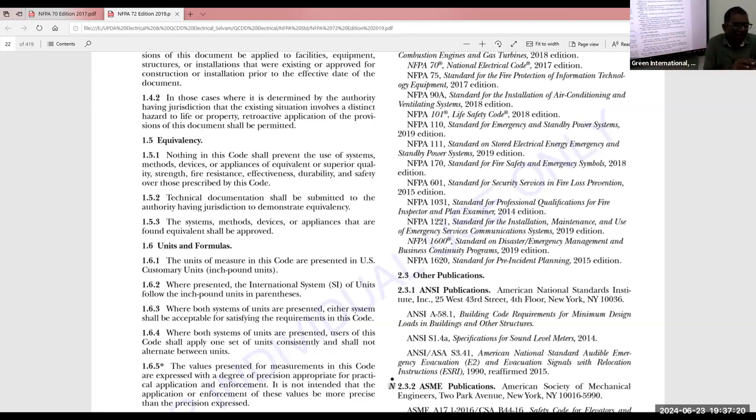Okay, let me discuss these areas in detail. So first, in the BOQ, they mention the generator. There is no need to get confused about prime generator or standby generator. We have a generator. Next, we have the word alternator. Then usually in the market or in the PVL, they mention Perkins, Cummins, MTU, different brands. So it refers to the engine. And in the offer letter, that is in the quotations, they mention the engine name, and they mention the alternator name also. So from this, what we understand is, generator means at minimum the engine and alternator.